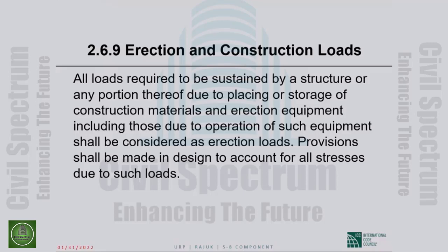So initially, obviously, concrete is short. It has to be temporarily supported before the concrete hardens. So we have formwork supported by shoring. There is a lot of pressure from the contractor to remove the formwork as soon as possible for reuse.